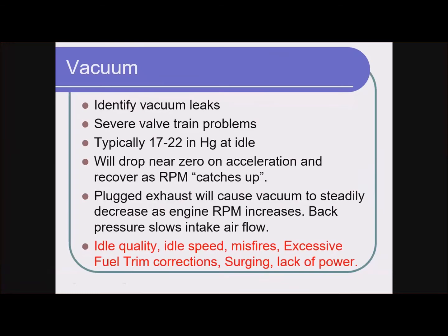With a plugged exhaust, the real key is that the engine won't accelerate, and the vacuum gauge is hanging out at a very low number, very close to zero. It just can't get rid of the exhaust, so it can't take in more air. It has no vacuum.